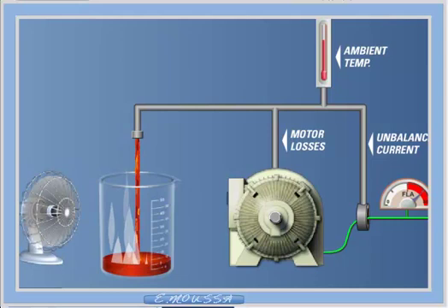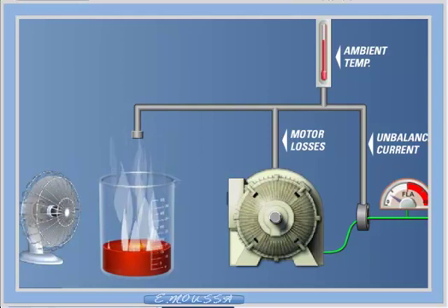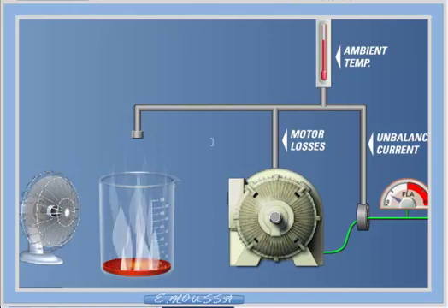Once the motor current drops to or below the motor's full load current rating, the thermal capacity used starts to drop. This can be imagined as the thermal energy slowly evaporating from the vessel. The rate at which the thermal energy is evaporated and the final level that it will drop to is a function of the motor data and load current, which will be covered later in this section. The vessel is also emptied when the motor is stopped at a rate based on the stopped cooling time.